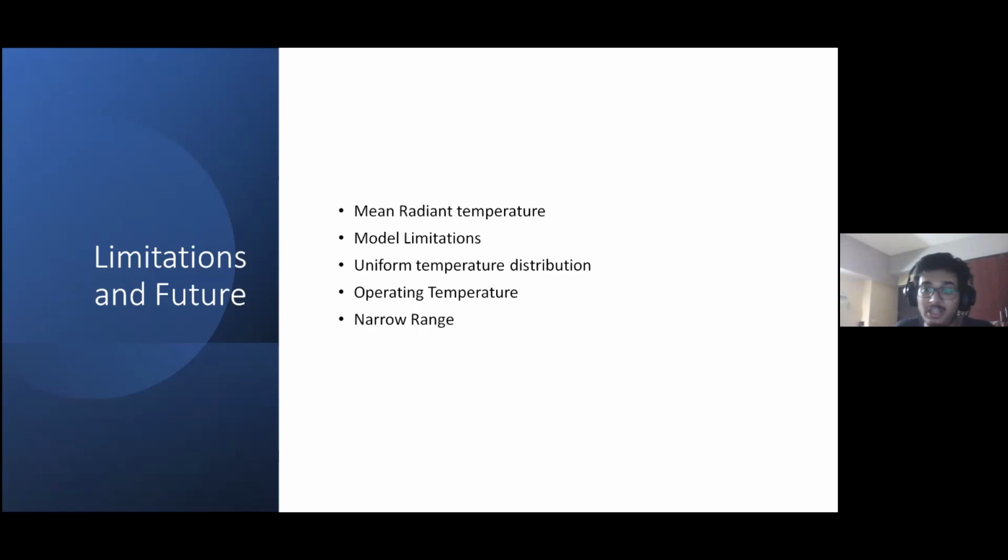You can also have heat being generated on the outside because of the skin friction of the high speed air molecules with the aircraft. This also heats up the external aircraft. So this will result in some temperature, or you can say a cooling load on the aircraft due to the external conditions. In this study, we've assumed that there's no heat load due to the external factors, which is of course not true. But this study can definitely be expanded to include that as well.